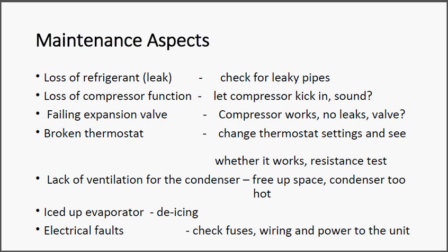And then also do a resistance test. Sometimes, depending on how the system works, whether the thermostat uses a high voltage or a low voltage, if there's some dirt on the thermostat and it's a low voltage, it will build up some resistance, and it might not allow the signal for the compressor to kick in. If it's a high voltage which goes through the thermostat for the compressor to kick in, you might get something called carbonization. So you get the contacts, there's some sparks and arcs, and over time they build up quite a bit of resistance, and it might just be too much for anything to go through to allow the compressor to kick in.